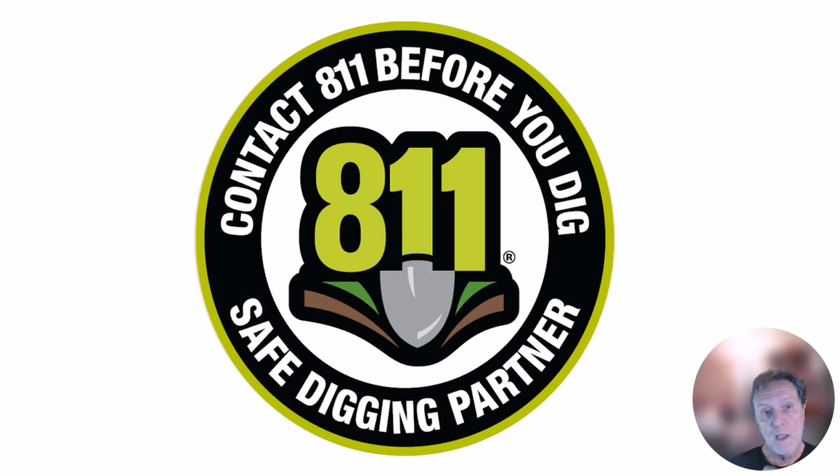So in California, we have a state agency that takes care of some of the locations for us. Contact 811 on your phone. They will come out to the site after you've pre-marked it, put stakes or paint where you might be digging or drilling, and they will let you know whether there are any utilities that are known by the state or the city and where they're located. Sometimes this isn't enough. On private property, the state agencies won't go into private property to locate utilities. So in those cases, it's incumbent upon the investigator to hire a private utility location service to go in with utility locating equipment onto the site and look for any buried pipelines or utilities. So that's to cover yourself